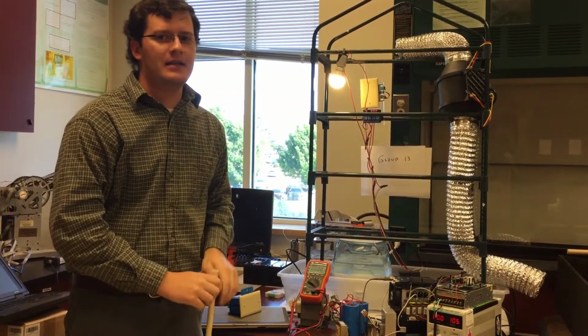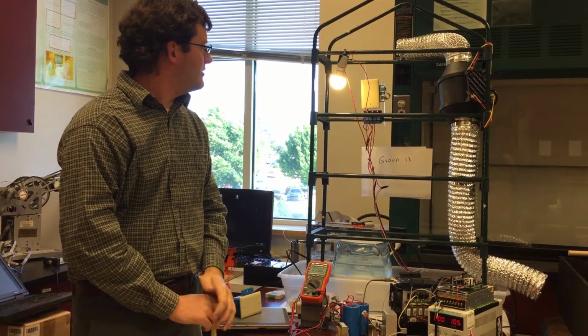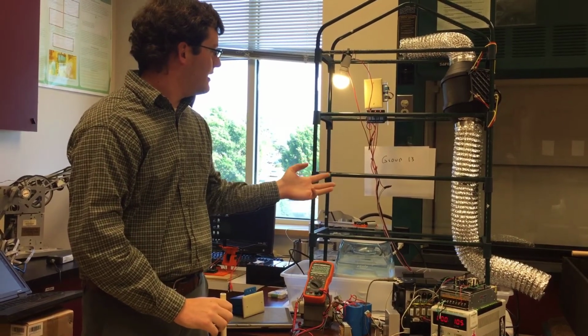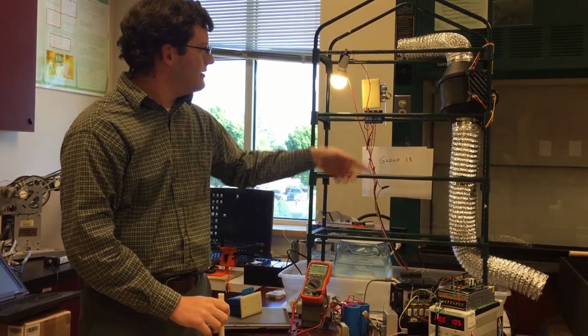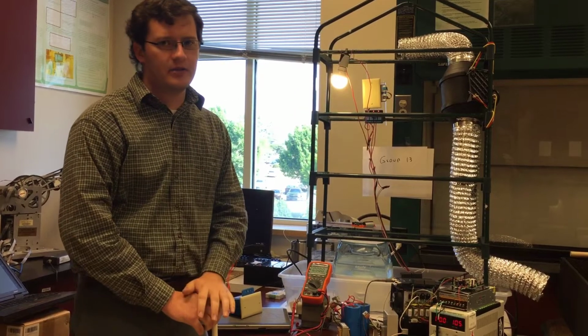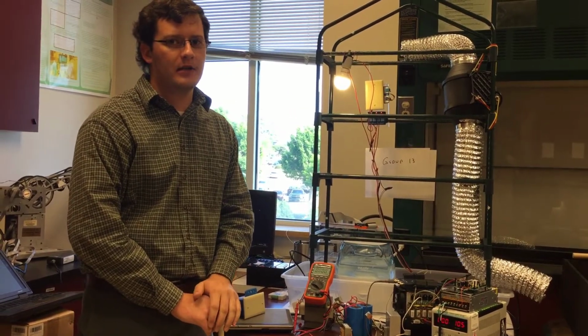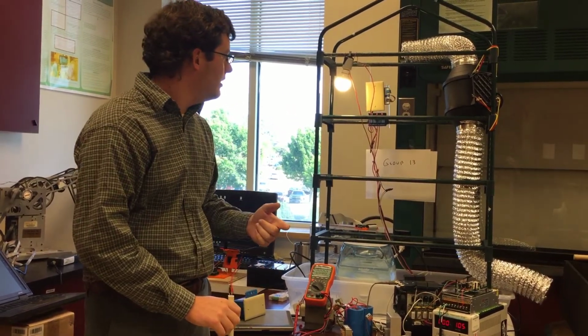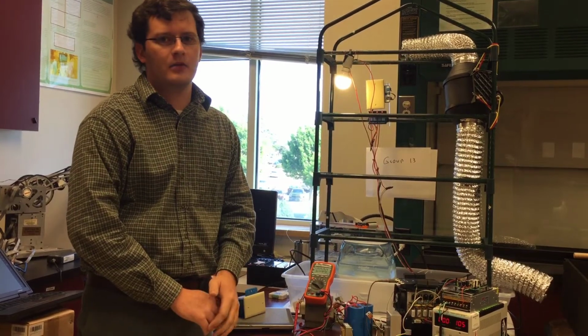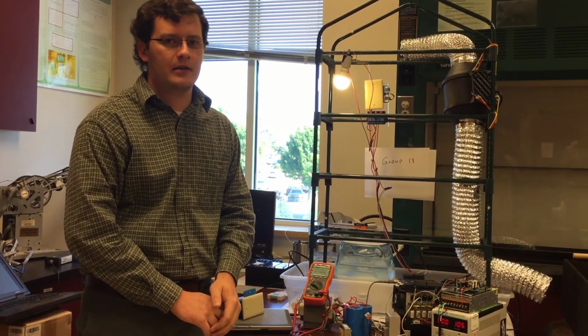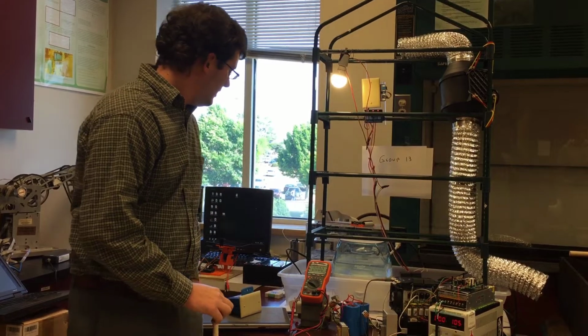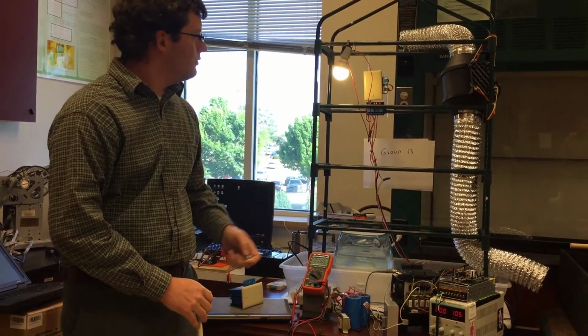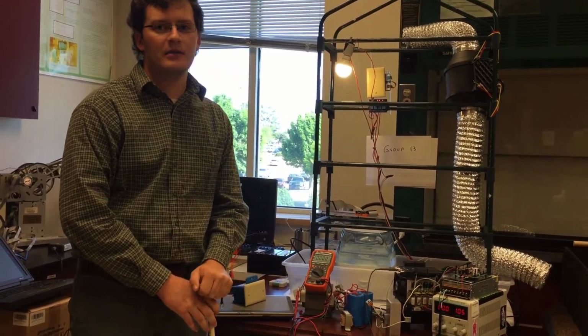So basically the DHT11 that we're using takes a couple seconds to work, as you can see. So we have it on a 3-second delay. So what you'll probably see is the fan's going to come back up, since the temperature takes less time to actually calibrate the sensor back to a normal condition. But then again, it might take up to 20 seconds or something before it actually works. So as you can see, all the inputs actually do work, and everything's changing based off of the conditions that we provide.